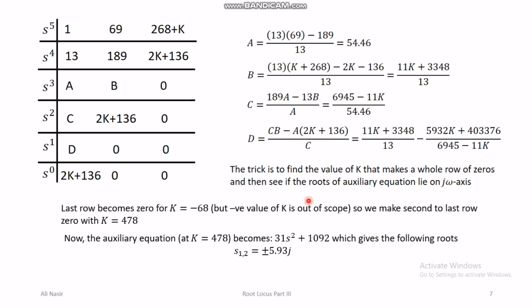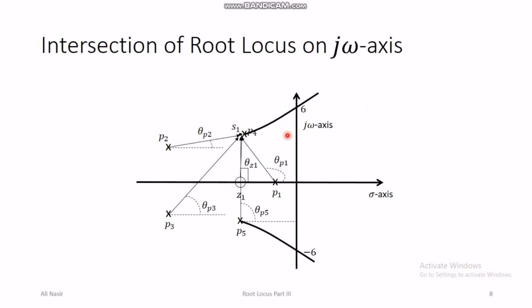So we can see pictorially here the diagram of the poles and zeros of the system that we considered, and for these poles we already calculated the angle of departure, which is around 40 degrees. So the angle of departure of this pole will be around minus 40 degrees.